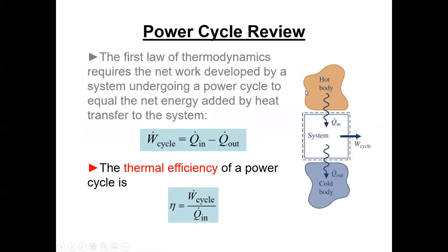So if we can increase the temperature here, we can increase the potential thermal efficiency. And from the Carnot cycle, if you keep the cold the same and increase the hot, you see that Carnot efficiency goes up. The power industry knows this and has for a long time.